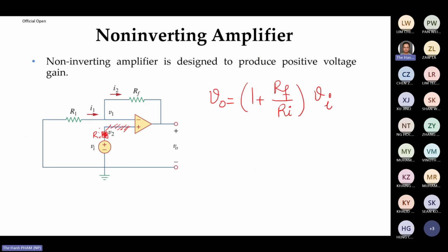So imagine if here you have internal resistance, right? Suppose this one is your sensor, with an internal impedance here. When you connect like this, there's no current running here because the input impedance is very high, right? So you can get the full Vi here, and then you can amplify. This one, I think you learned before, okay? If you want to know how to prove it, you can ask me.